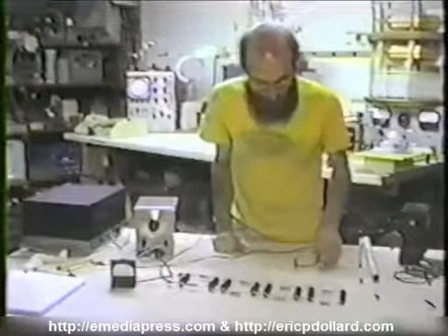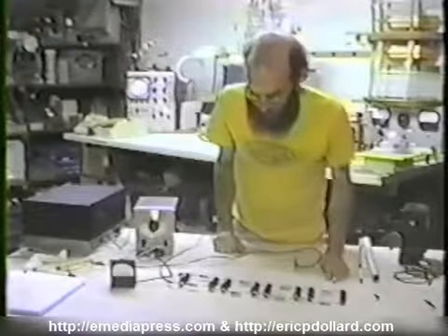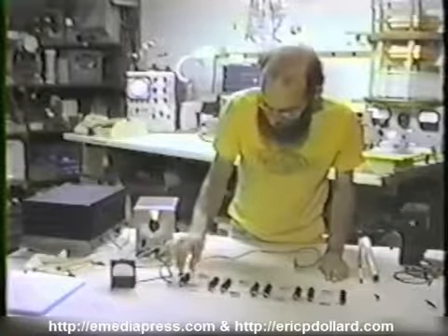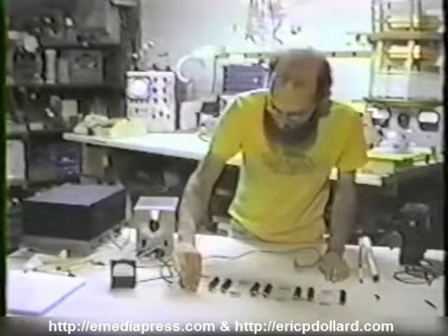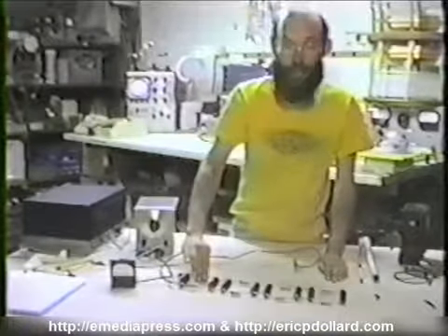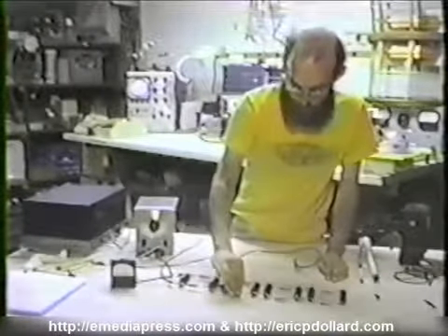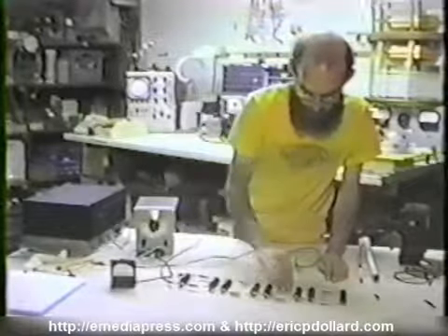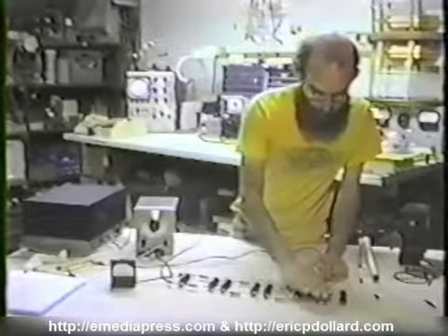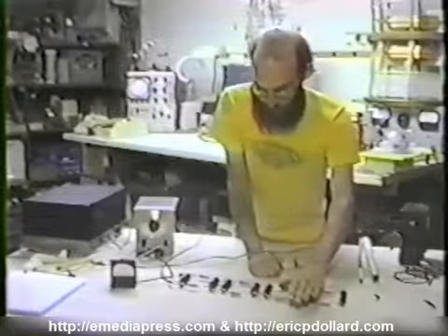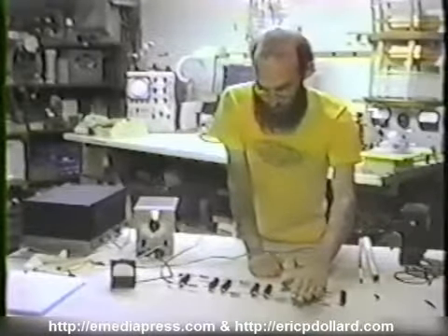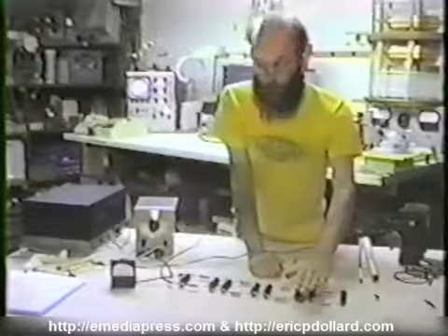And we'll do our heat check again, see where the heat's coming from in here. Feel our input coils, relatively cool. The input capacitors are quite hot. Go down the line here, capacitors are cooling off, but the coils are very, very warm, this end. So now we have the situation where the heating effect is turned around from where it was before.